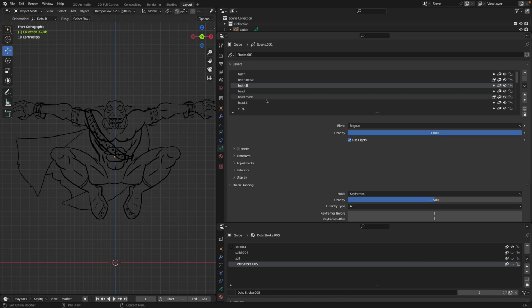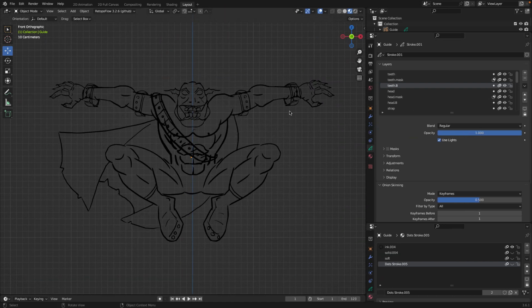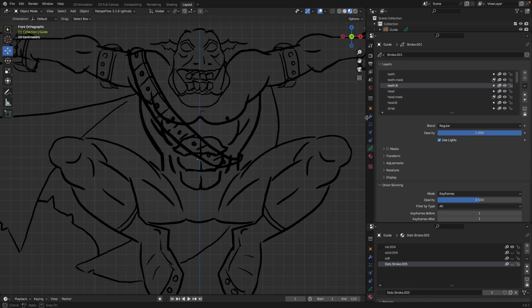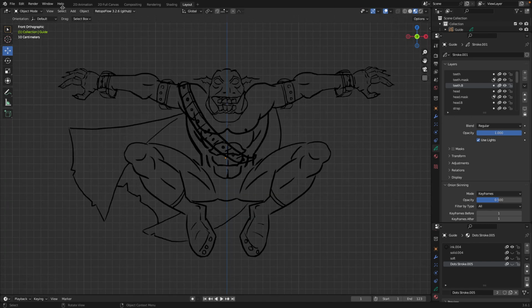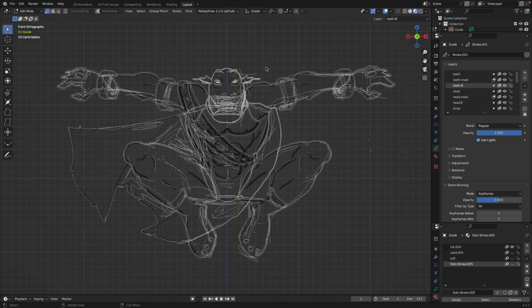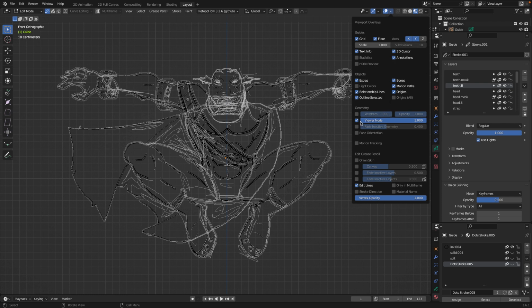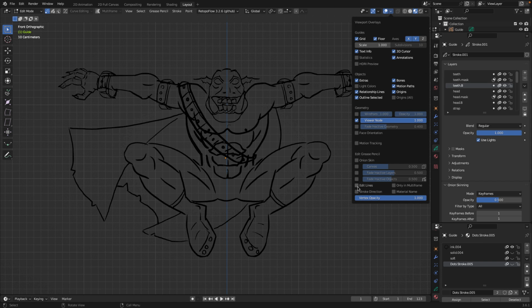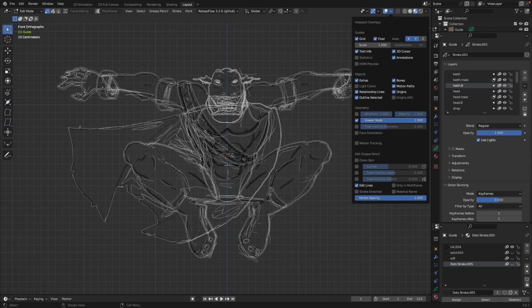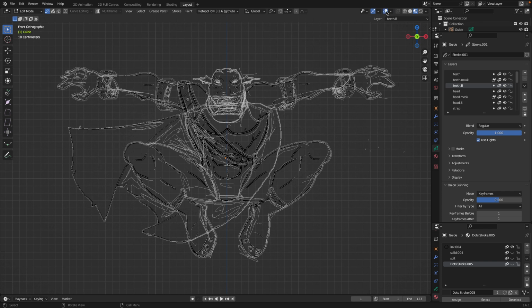That's easier instead of going to each one and separating them. The faster the better. So I'm just gonna go to edit mode, and so it doesn't look like this, I'm just going to either come over here, edit lines, get rid of this one, or simply select this part over here. Either one would be fine.